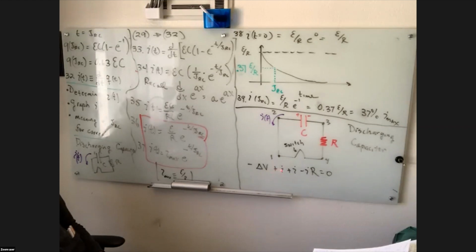Okay, so first of all, good effort, but those terms don't make any sense, since they don't have units of voltage. Kirchhoff's loop rule is a sum of voltage, right? You're saying there's a current in that leg. Okay, there is, but this is not a sum of currents, this is a sum of voltage. Voltage plus current is apples and oranges. Minus IR has units of voltage, but I has units of amps. So these things shouldn't be there.